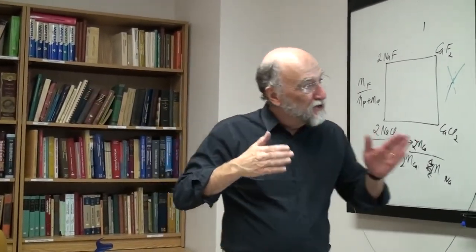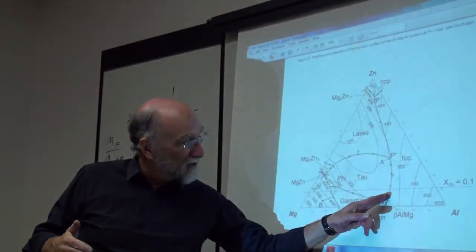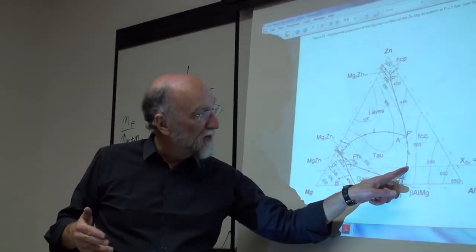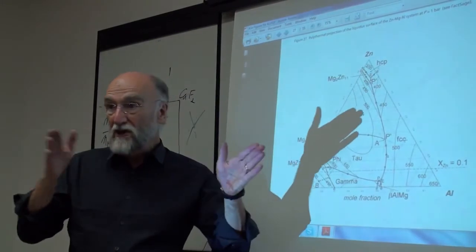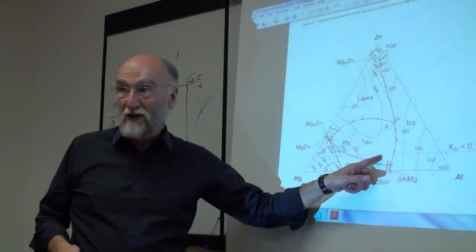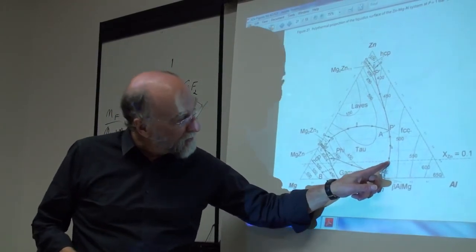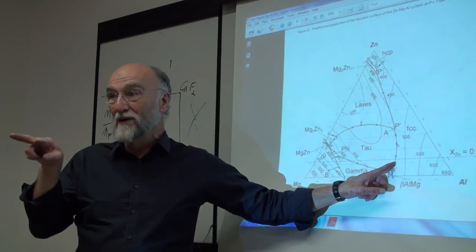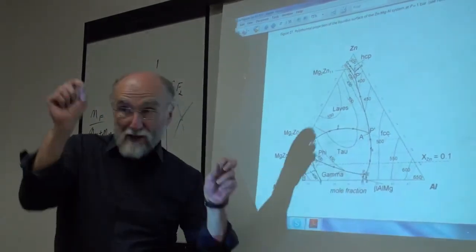Now you change the temperature, and as you change the temperature, you keep yourself right on the line at which you have, say, a liquid phase in equilibrium with zero amount of each solid phase. This is the composition of the liquid in equilibrium with the two solid phases. So if you have a liquid exactly on that point, then it's in equilibrium with the two solid phases at zero amount. Okay, so you then follow it as you go down in temperature.